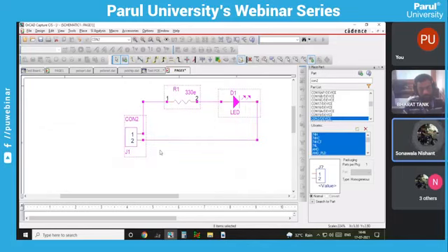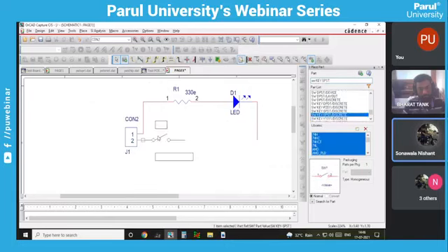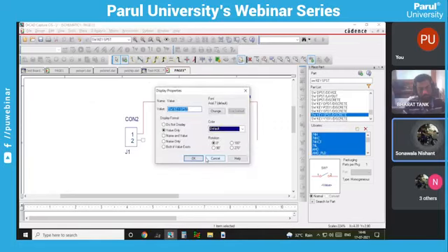Once you power up, it directly gives you the power. What we want to do is put one switch over there so that we can turn the switch on and turn it off. So let's simply take this switch. We will choose a 2-pin switch. There are different switches it shows us. We'll choose the switch which has only 2 poles. We are choosing this switch and name it on and off switch.